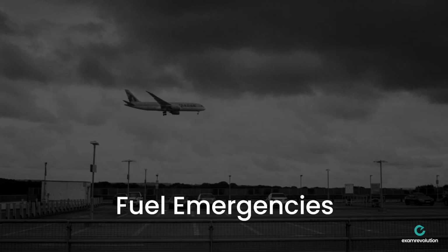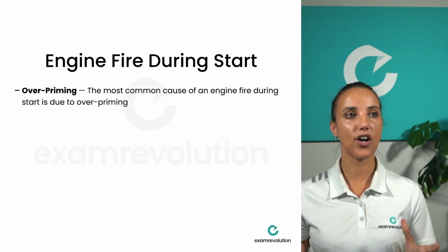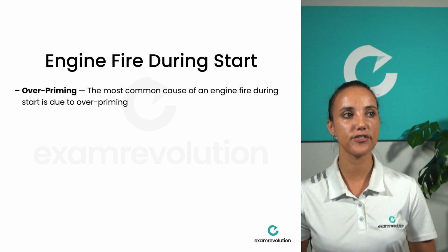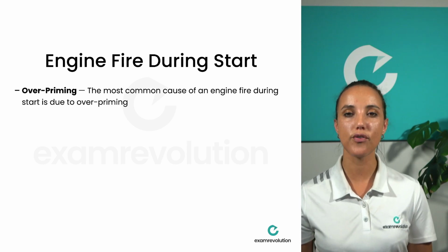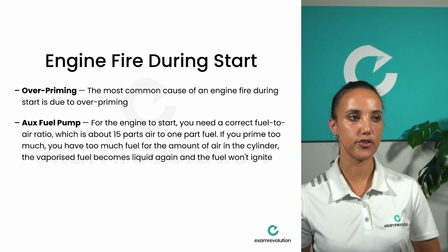Let's now have a look at some fuel emergencies. Now, during start, the most common cause of an engine fire during start is due to overpriming the engine. So what happens when you overprime during start?